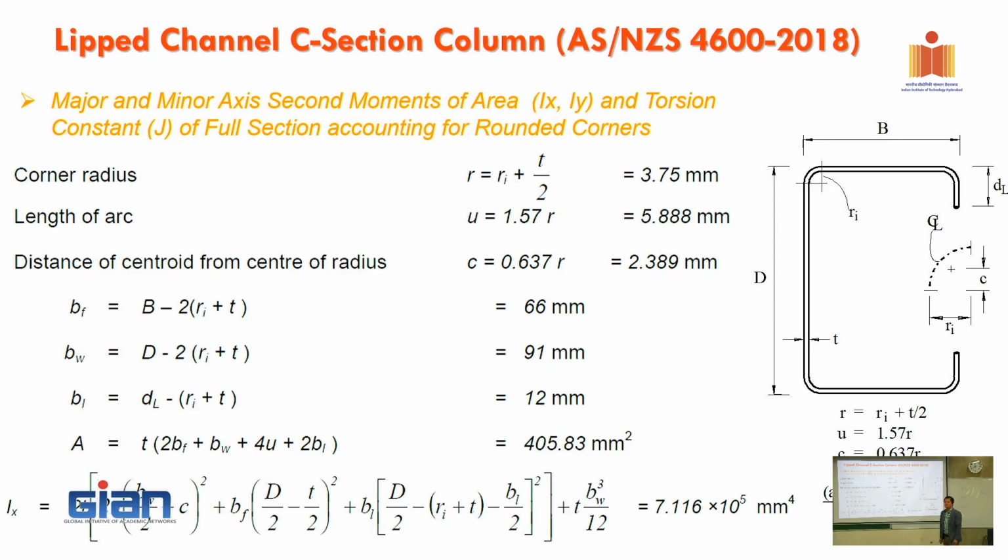It's just based on structural mechanics, so whatever you do, you can calculate. Inertia equals the length times thickness to the power of 3, and that may not be high, so it could be omitted in the calculation. So taking all the flanges, lips, webs and corners as line elements, omitting the thickness and only taking the length of the element.